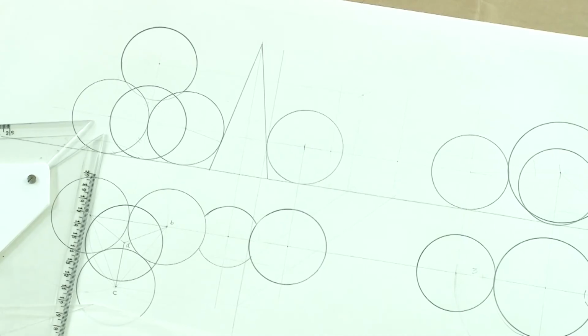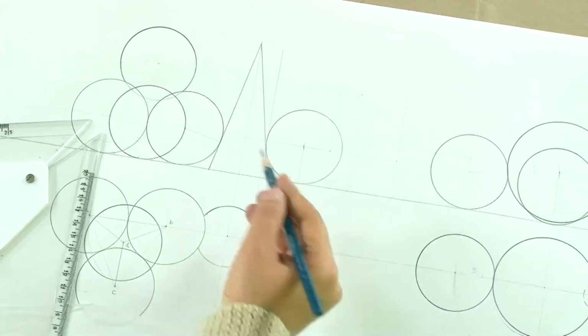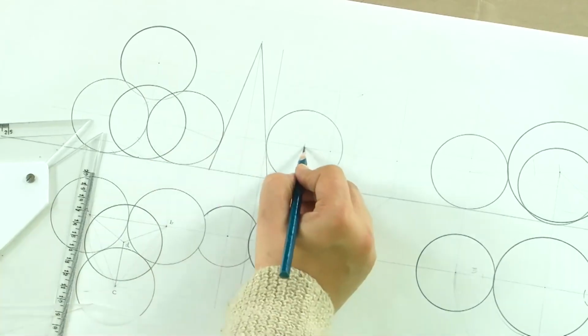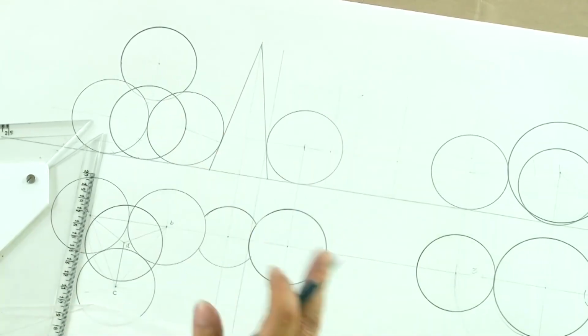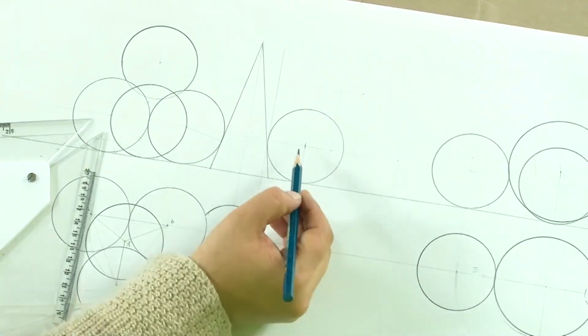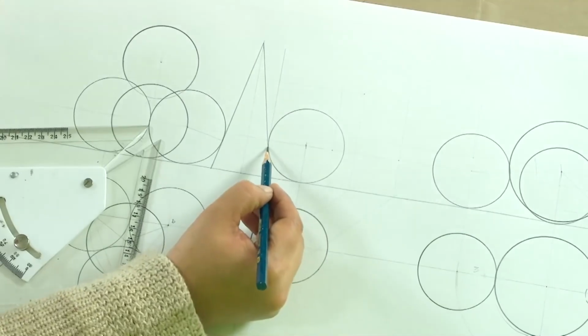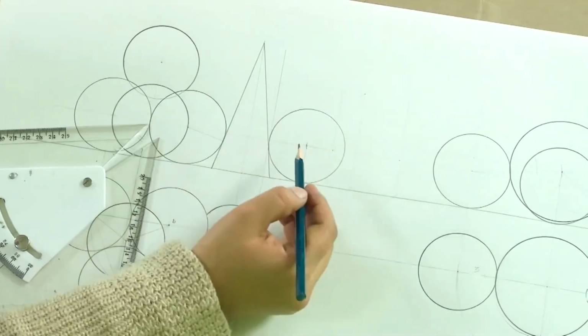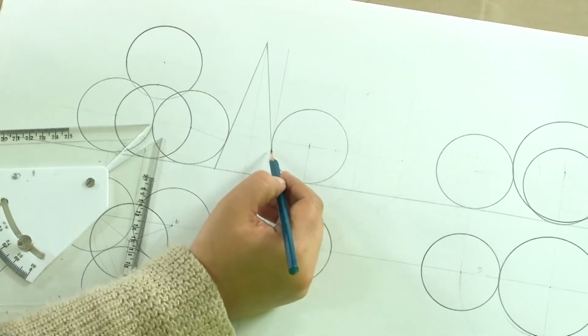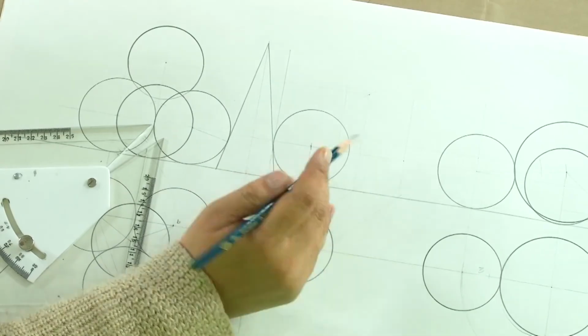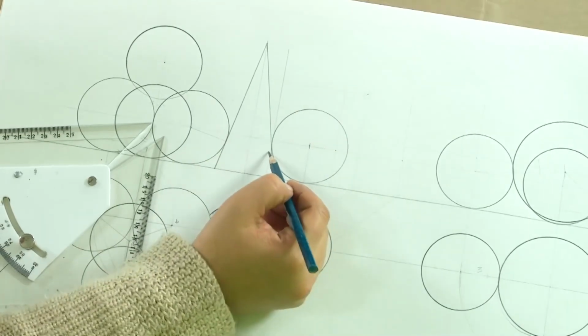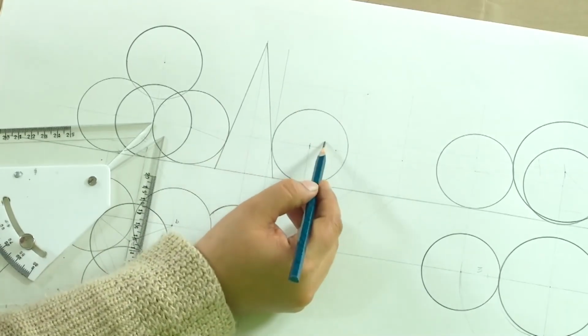The only thing that we have to keep in mind is where is the center of the sphere, and always remember that the sphere will be using one of the surfaces of the cone or whatever solid as a tangential surface. So, whenever we make this, we will have to take the perpendicular bisectors.